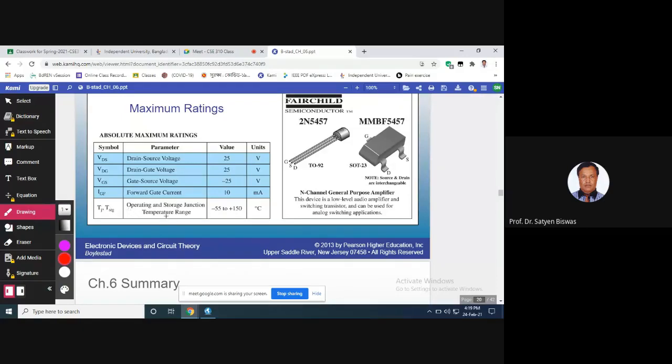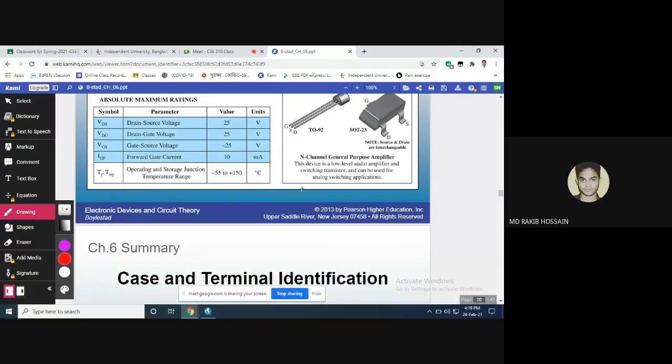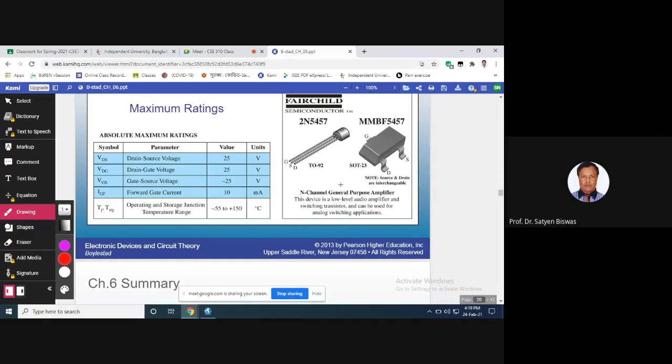And the operating temperature range, right? This one. Are these two the same? No, this is one company, and this is another company. Some companies make it like this one. This is a 3 terminal device: gate, drain, source, and this one also is gate, drain, and source. Different companies make it in different ways. Here, gate is on the left side, source in the middle, drain on the right, but here it is the opposite.